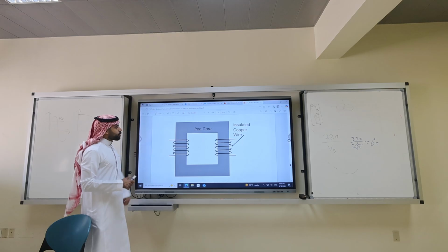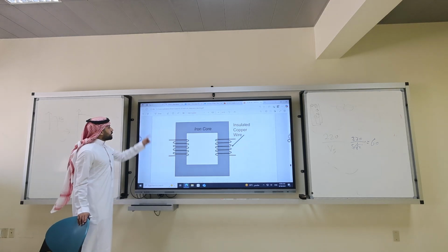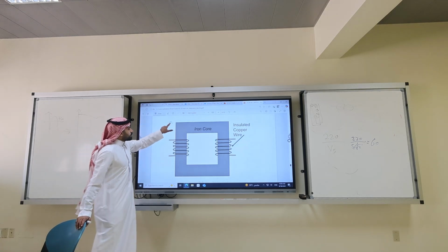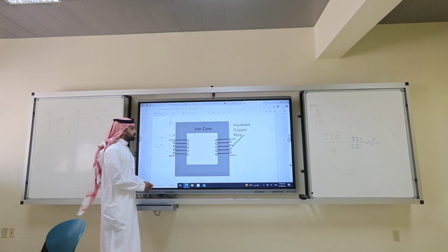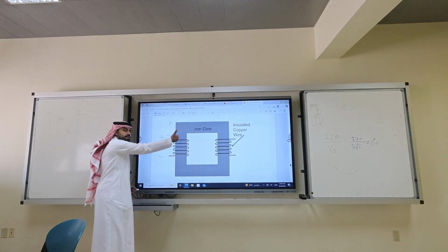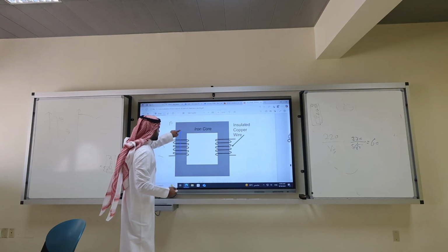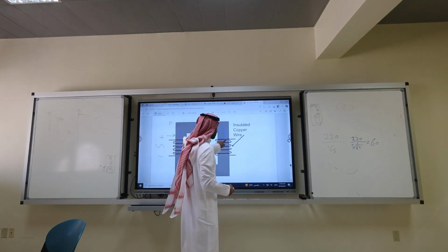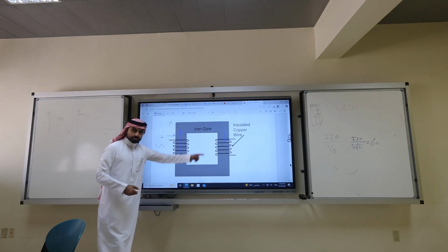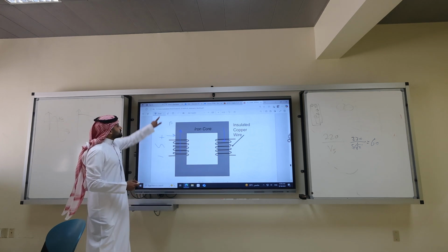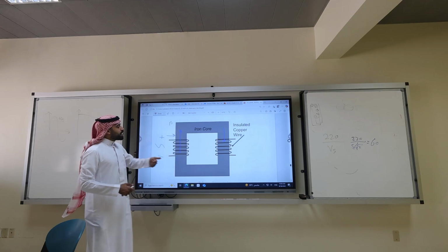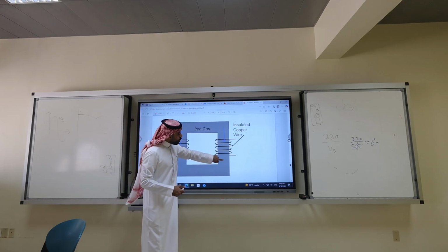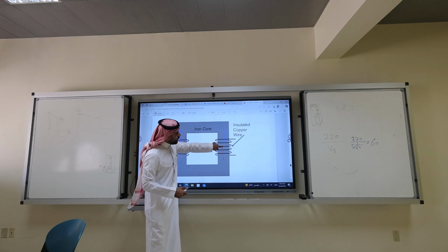Let's look at this transformer. Can we apply it? Let's say this is the primary, and we apply a voltage here, and it's AC, and there is an induced voltage. What is the direction of the flux? Up. What is the direction of the original flux? Down, down here. What is the theory telling you? There is an induced flux opposing it, the red dashed one.